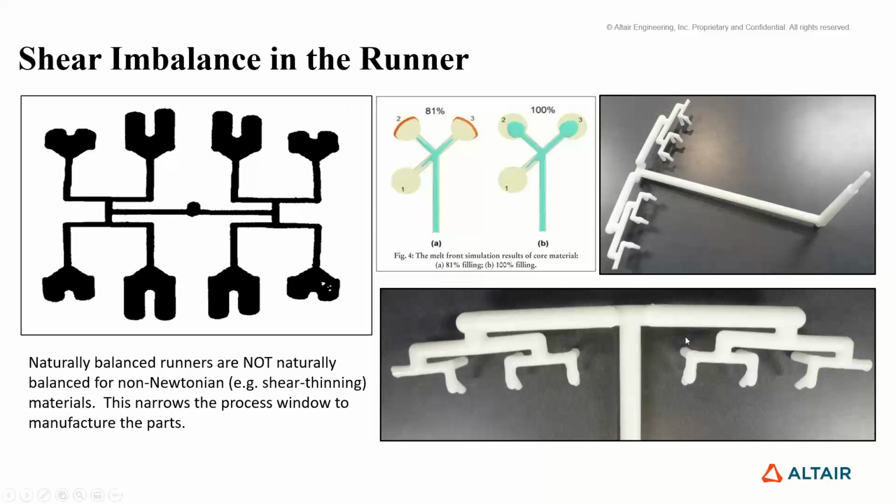What you see here on this was an 8-cavity mold, and they were having so much trouble trying to fill all the parts that they ended up shutting off the outside 2 just so that they get 6 parts out of their 8-cavity mold. Now, if you've never done costing for that kind of thing, that's really expensive to only get 3/4 of your production with every shot. Your overheads just jumped. So kind of expensive. I have an example of this queued up to show you. This is Dr. Yokoi's model, so you'll see that in just a minute.